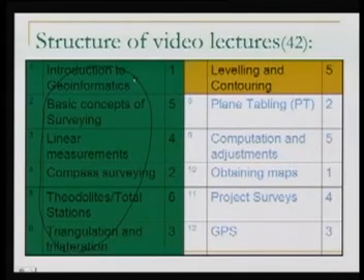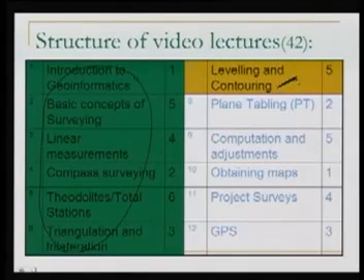Now this is all what we have done so far, and mostly we are talking about the horizontal control so far. We looked into some instruments which will measure the horizontal angle or vertical angle also, the linear distances or the sloping distances, and we can establish the control in horizontal. In case of triangulation in our last module, those triangles along with the vertical angle measurements can also be used for trigonometrical leveling, and that way we can establish again the vertical control. Now we will look into detail about this vertical control today, and this is what our module number 7 is.